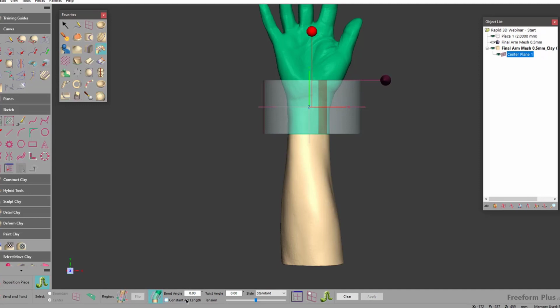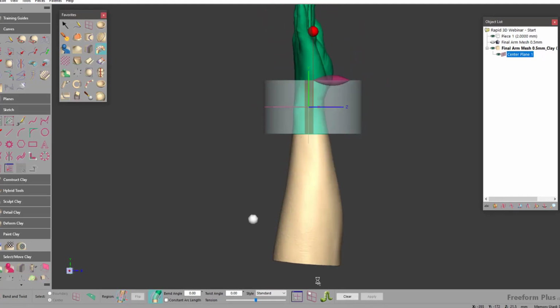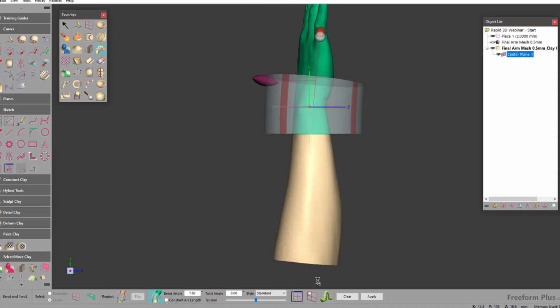I'll just hit undo to those changes, and then we'll toggle back into it again here. And what I like to do is move with more precise movement than that. So I'll rotate to the side, and if I'm trying to correct it in this direction, I will just barely bend it and then come in and type in a specific value and say that, okay, that needs to bend 5 degrees, and I'll just twist it just a little bit.